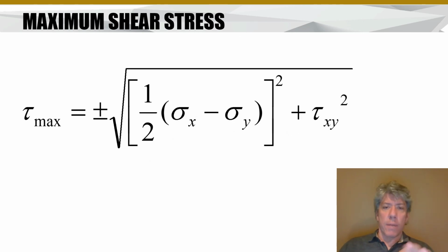Now, the maximum shear stress, you'll notice that this is actually the dimension a squared, that's the first term, plus b squared. That's really what it is. And notice that these stresses, tau xy, sigma x, and sigma y, come from the initial simple element that's relatively easy to analyze, right? We took an arbitrary cut because that cut made it easy for us to calculate the magnitude of all the shear and normal stresses. Well, the nice thing about it is once we get those, we can plug them into this equation and calculate the maximum shear stress. Now, interestingly enough, as I said, this is just the R, the capital R. It's the radius of the circle. And so A is the length of that triangle's base, and B is the height, which is just tau xy. So you see the negative sign here that should be on that Mohr's circle slide that I worked with a moment ago.